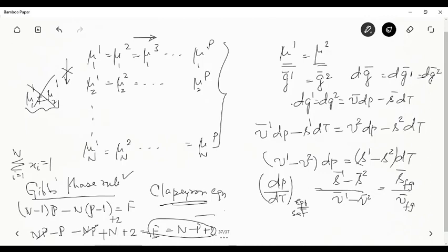And in order to do that, when I equate the Gibbs functions, it gives me the condition that the chemical potential of each species in that multi-component multi-phase system should be equal for phase equilibrium to exist, for all the n species. With that, we are able to get, for a single component two-phase system, the Clapeyron equation, and the number of independent variables required to specify a multi-component multi-phase system is given by the Gibbs phase rule, which says F is equal to n minus P plus 2. So this is what we have done in today's class.